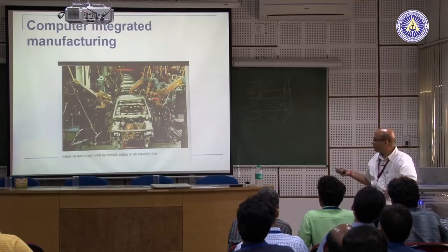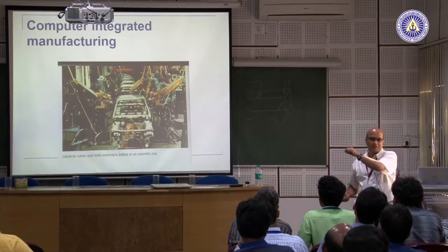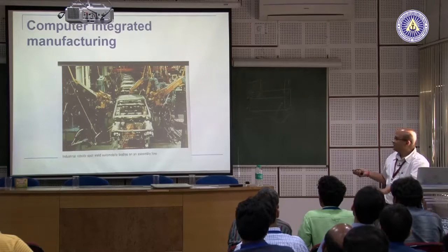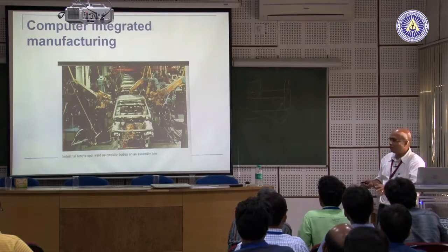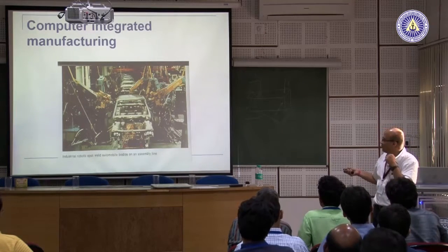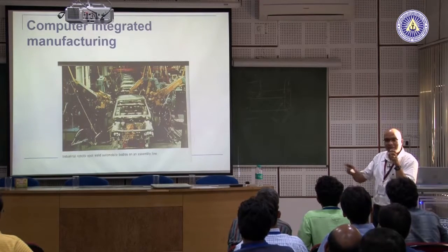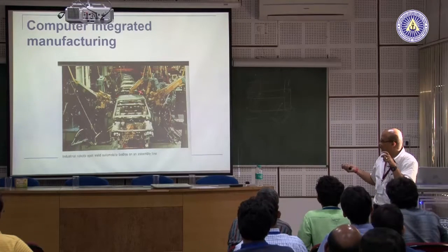The robot program will now be written such that these robots go to those points, okay, and perform the weld. Okay. And then a simulation is done, in the CAD model as well as in the robot model. Then if in the simulation everything is fine, they will come to the real world. In the real world they will make this car body out of plastic or something like that, and then the tool of the robot also will be made with plastic or wood. Okay. Then they will run it for maybe months. Okay. They will try and see whether there is interference between the robots, is there something going wrong somewhere, is there a damage anywhere.